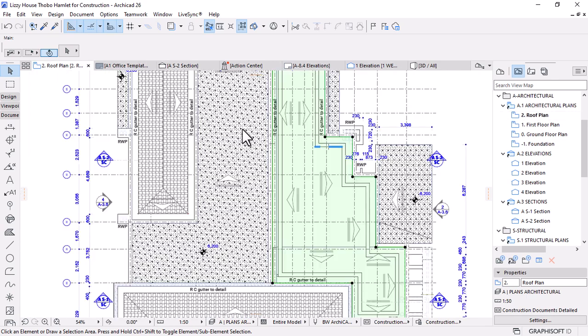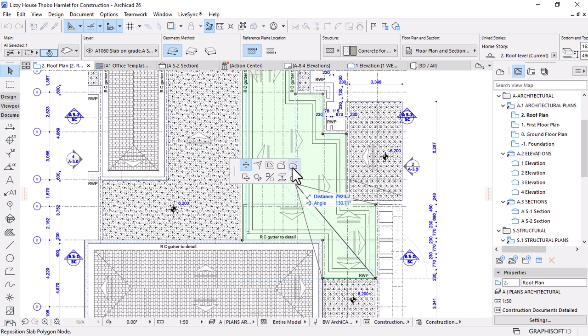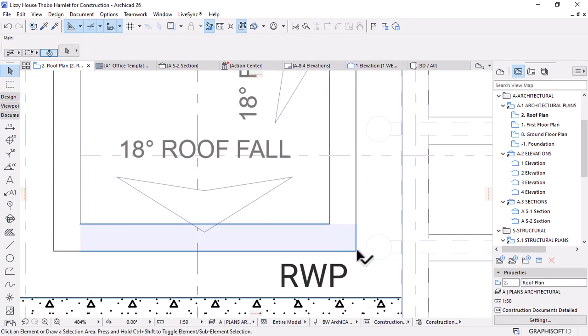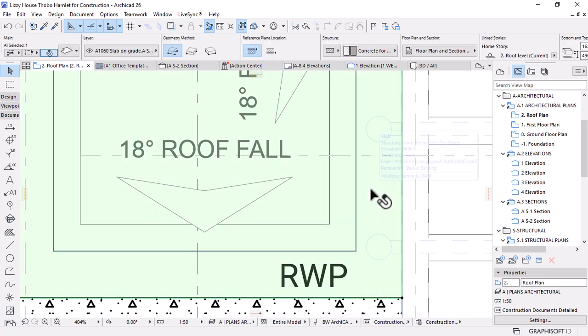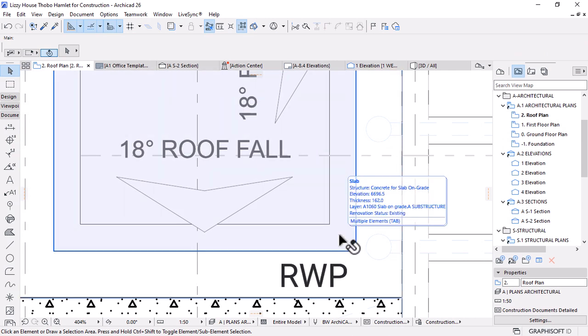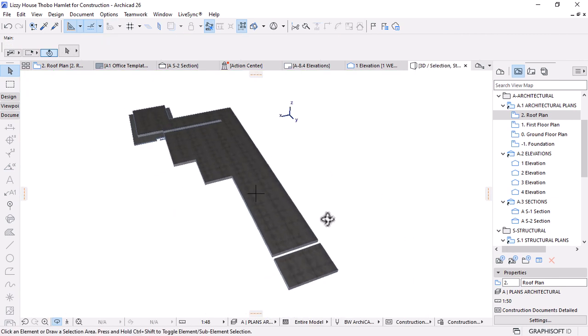So what I'll do, go back to the roof plan and then click this. Let's drag or offset a copy to the inside like that, and then I'm going to use that slab to subtract a polygon. I'll try by all means. I can do it on 3D. Let's try to isolate the two slabs.